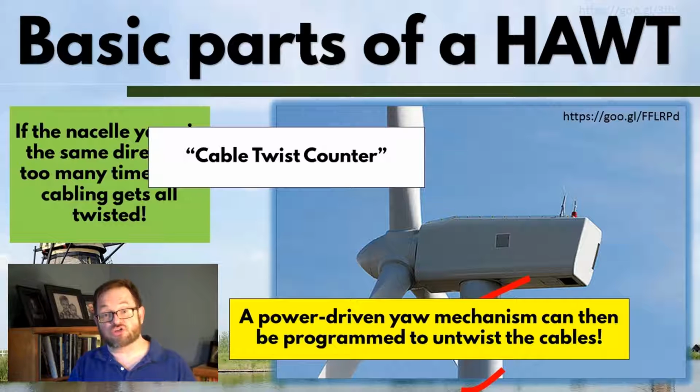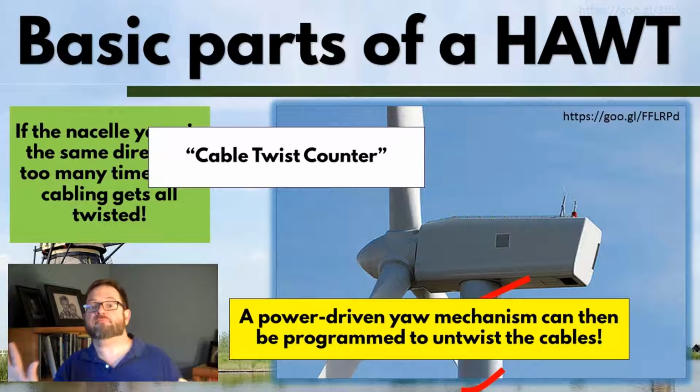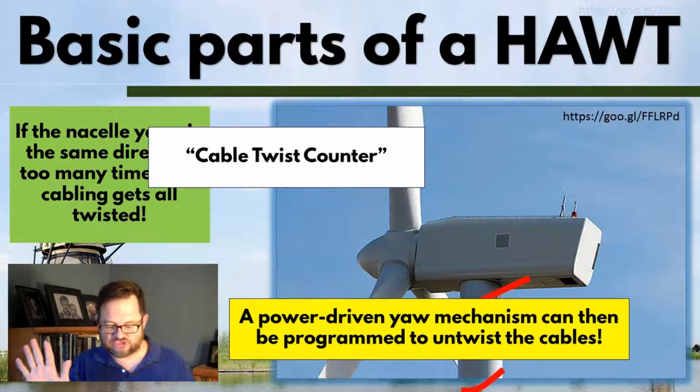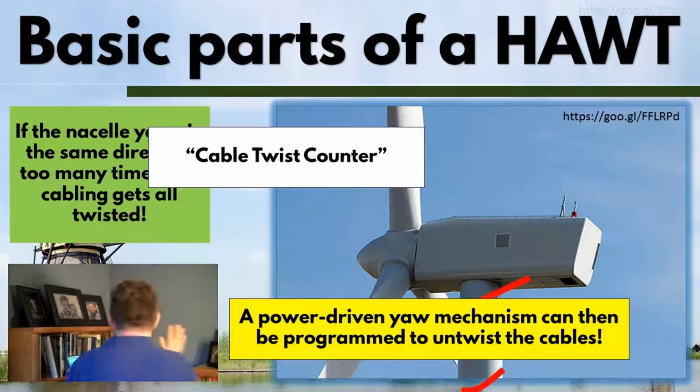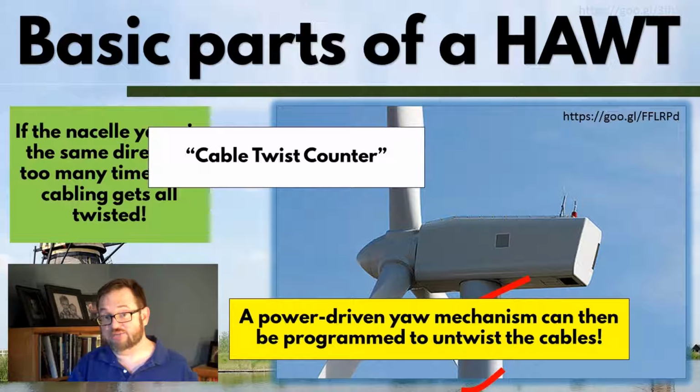it's active yaw control, where there's actually motors controlling the yaw, what you can do is stop the windmill by adjusting the pitch of the blades in the turbine, and then literally powering the turbine through some rotations to make it untangle. So drive it the opposite direction a few times.